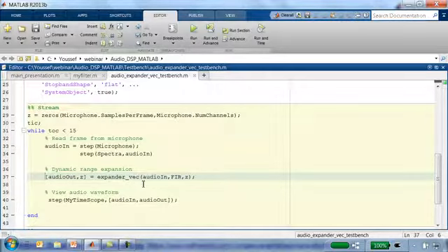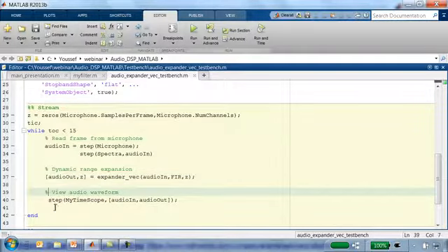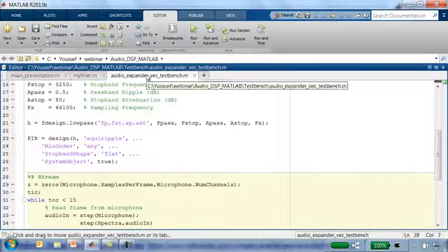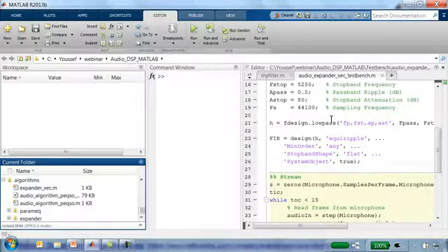Where I take the audio input and then I monitor the threshold of the envelope. When it drops below a certain level, my gain processor lowers that signal to an even lower level and smooths out that gain before it applies it to the input audio signal. And then I will show you, by calling step to my time scope, both the input audio signal and the expanded signal. Okay, before I run it and see how it works, let me show you the expander code algorithm.